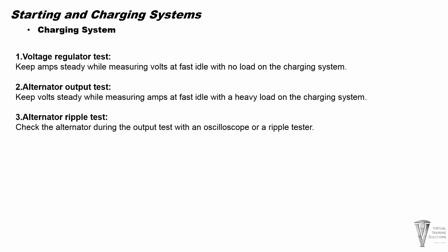Check the battery's no load voltage. A fully charged battery should deliver 12.6 volts. If it's below 12.4, charge the battery and retest the system. During this test, you should load the battery with 1/2 of its cold cranking amp rating for at least 15 seconds. During this test, battery voltage should not drop below 9.6 at 70 degrees Fahrenheit.